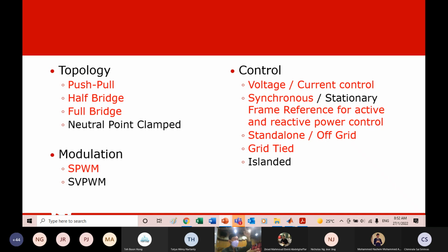Then the guy goes and touches the live wire, of course he gets shocked. That's why nowadays, when you want to connect a system to a house, you must use an inverter that has the islanding detection feature. That means the inverter will have to confirm there is power from the grid first, before it generates power. Or else it will trip itself, for safety purposes.